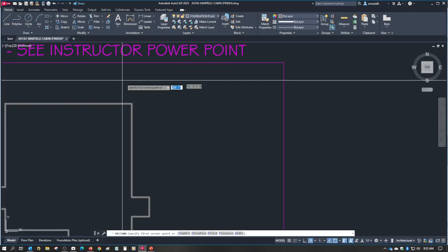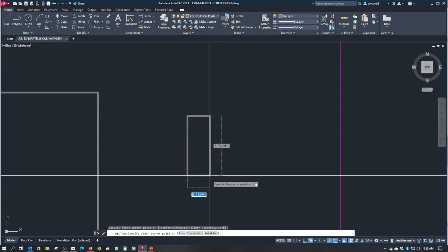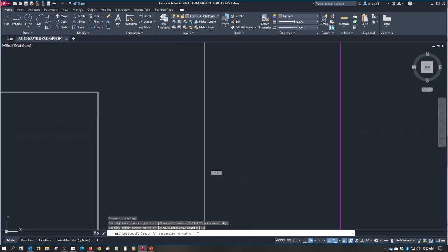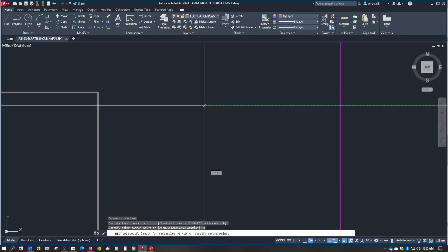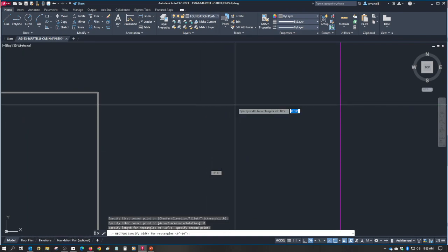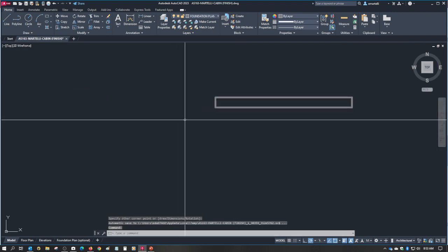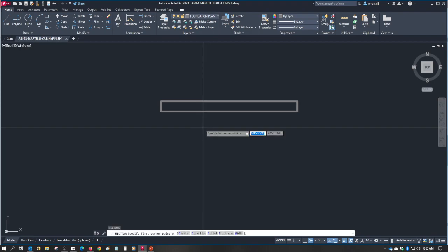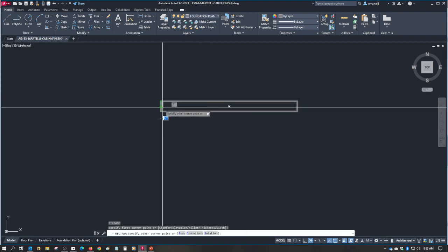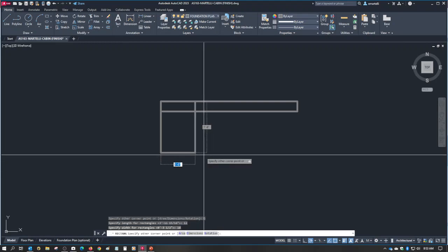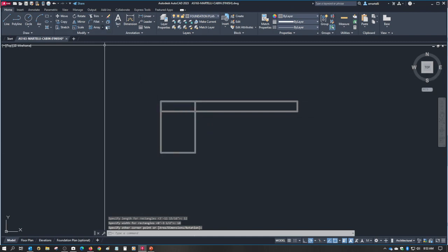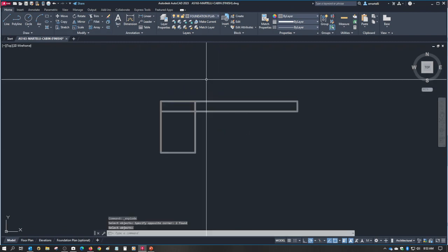I'm going to pick rectangle, start a rectangle, and press dimensions. For the width, think in terms of X. I'm just randomly going to choose 2 points, but the height is going to be 3.5. That's going to represent my slab. Right click, repeat rectangle. Now I'm going to start a rectangle here, press dimensions, type in 12, enter, 18, enter, pick quadrant number 4. Okay, now I need to explode both of these rectangles.